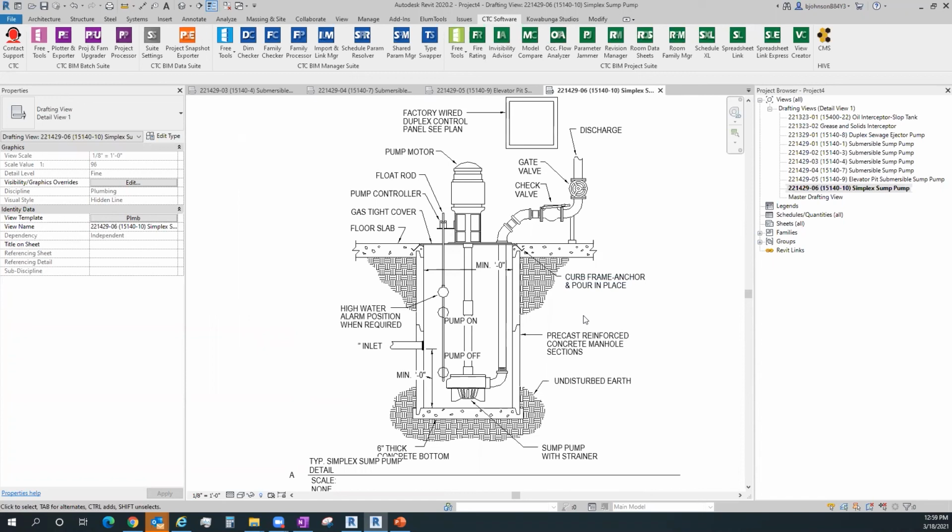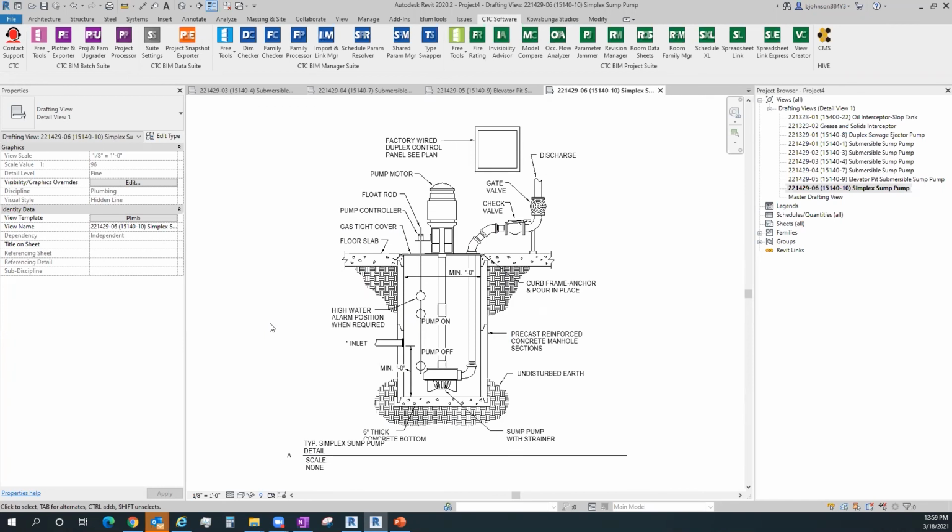And usually you're going to want to process at least 50 to 100 manually, figuring out what you have in CAD across each discipline that you're working with, and how many different things you can import that don't explode themselves. There will be extra little valve pieces that come in as blocks that have to be exploded even 2, 3, and 4 times to get them exploded all the way down to line work. Things like that are always going to be cumbersome, depending on how your CAD blocks come in. But it looks like I am just about out of time for today.